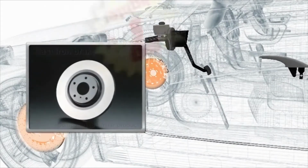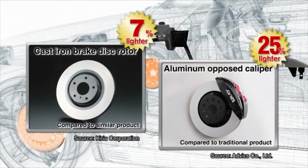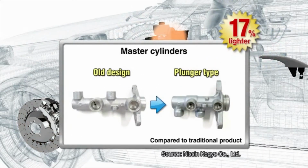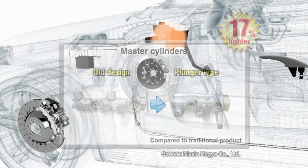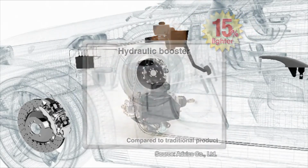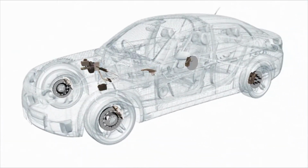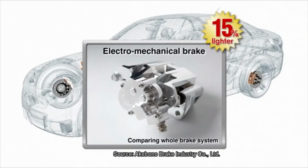With improvements in the cast iron for the brake rotors and the use of lightweight aluminum calipers, brakes are also smaller and lighter. Efficiently designed brake boosters also help minimize its size and weight. Electromechanical brake uses a motor to apply braking pressure, eliminating the need for brake boosters and hydraulic lines. With a simplified construction, the braking system as a whole becomes more compact and lightweight.